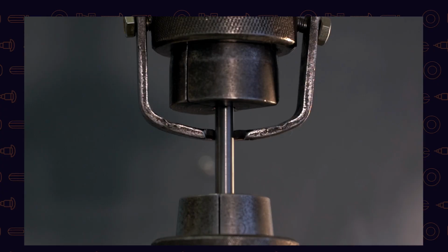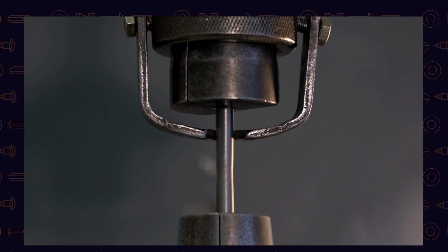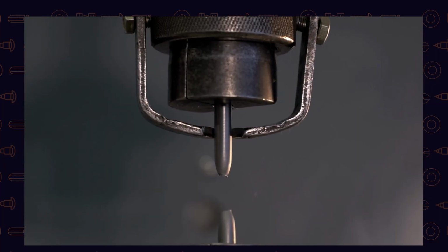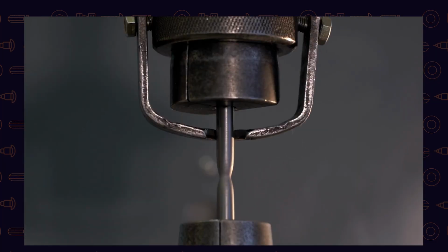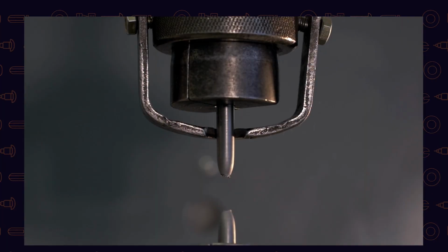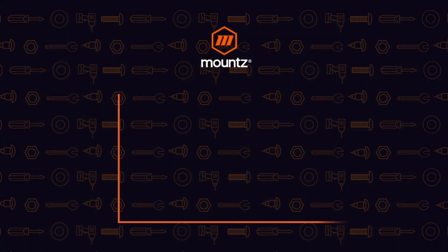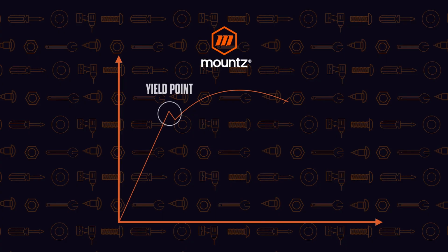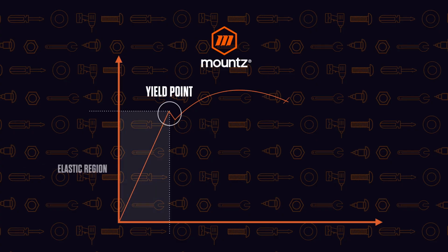However, if we stretch the fastener too far, we'll get to a point where it will begin to deform and then finally break. The point of no return is called the yield point. Basically, we've taken that fastener to a point at which it will no longer return to its elastic region, or its ability to return to its original size.